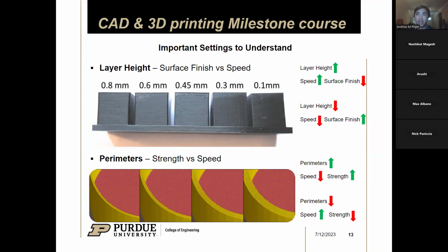So if you design any engineering parts, the orientation at which these layers are placed is something you want to factor in, because the bonds are weaker in that direction. If you were to hit it in that direction, it can shear and break. But that's getting a little bit more technical.